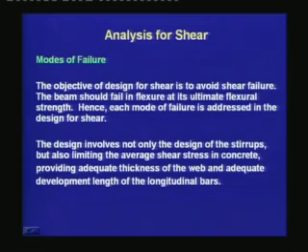Once we have understood the modes of failure, we can understand the objectives of the shear design. The shear design includes not only the design of stirrups, but also other detailing requirements which check the different modes of shear failure.